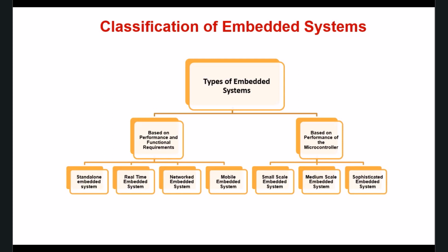Okay, 8-bit microprocessor or 8 or 16-bit microcontroller. The medium scale embedded system. The next embedded system is the medium scale embedded system, and these are basically designed using a 16-bit microprocessor or a 16 or 32-bit microcontroller. And the third, sophisticated or large-scale embedded systems, are those developed using 32-bit or more microprocessors as well as microcontrollers, or the controllers used to develop the device.